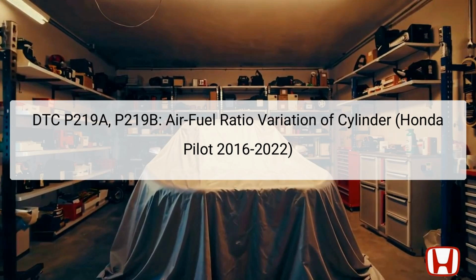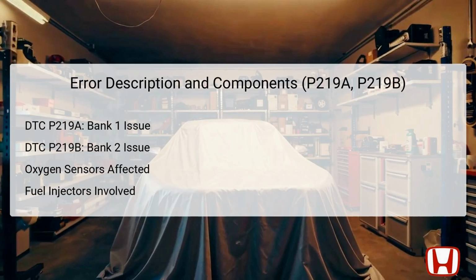interconnected. Additionally, reviewing the vehicle's onboard diagnostic system, OBD, data will provide crucial insight regarding the state of the cylinders and related components. DTC P219A indicates an issue specifically with the air-fuel ratio variation in Bank 1, while DTC P219B highlights the same variation for Bank 2. The vital components involved in these discrepancies include the AF sensors and the fuel injectors.